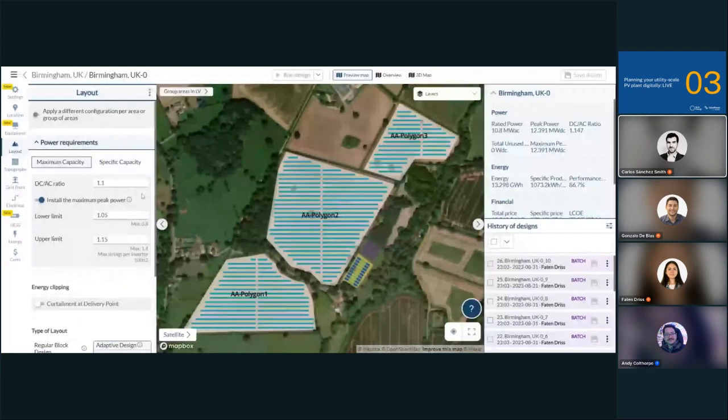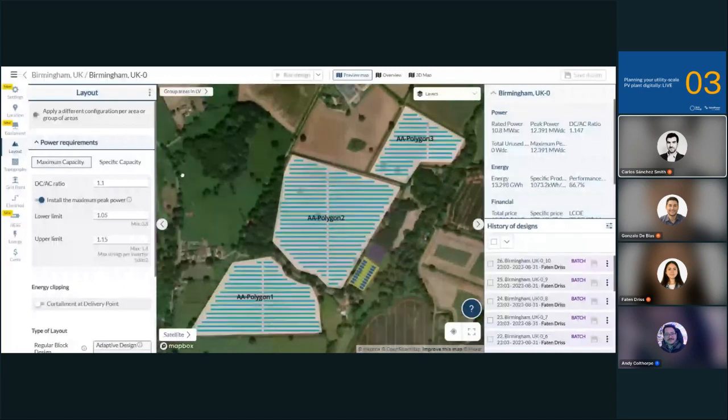So a good tool that the software gives you is to optimize this solar plant using different DC-AC ratios. Well, we'll see it later on the pitch optimization and tilt optimization, but you can also do it on DC-AC ratio, and you can find that for bifacial panels, the better value normally is between 1.05 and 1.15.